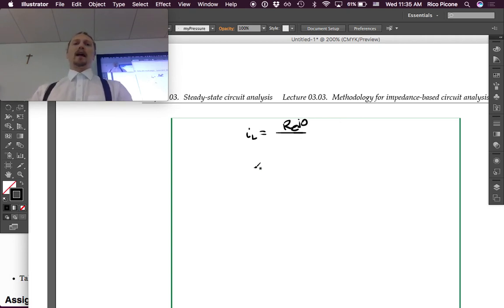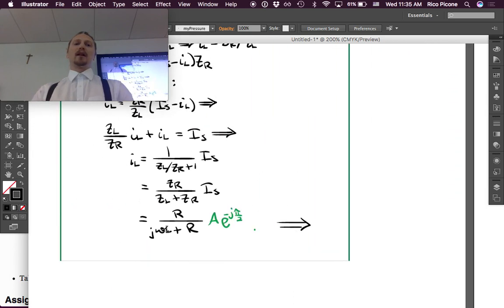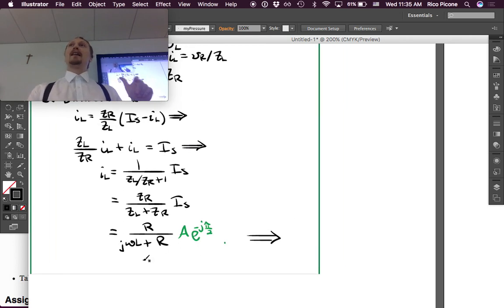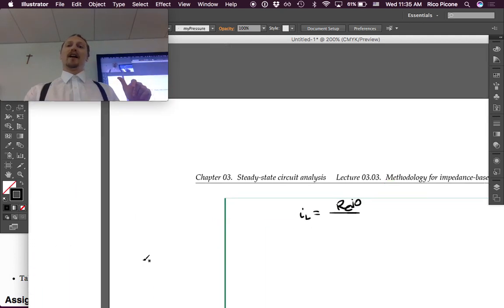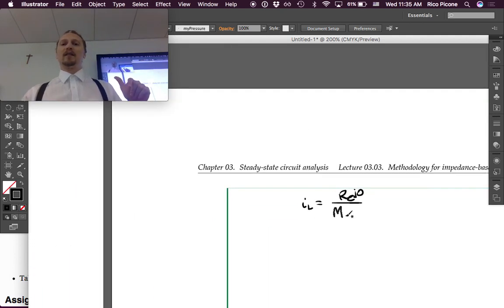And then we had this complex number here in rectangular form, right? Real and imaginary components. We know we can convert that using the Pythagorean theorem and arctangent into a phasor form. But we're also not really feeling like writing all of that because it's big. So we're going to take a little shortcut and say, whatever that magnitude comes out to be, we're going to call that M1, magnitude 1. And we're going to call whatever the phase comes out to be phi1.